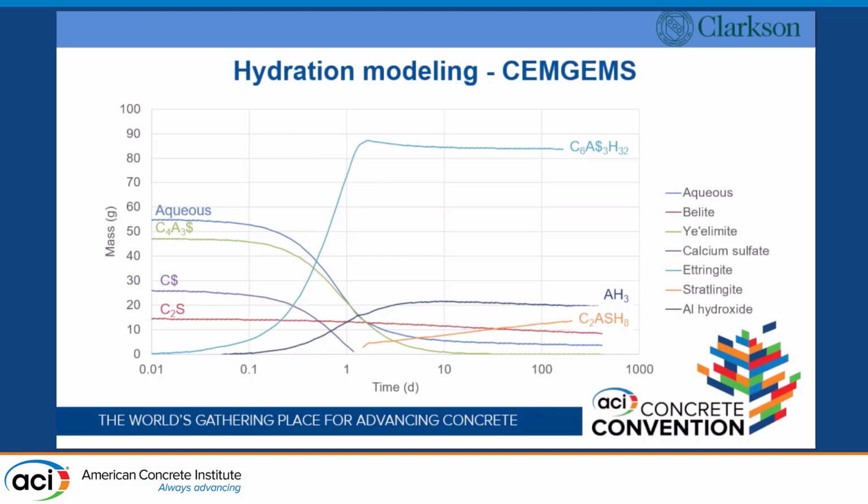So when we talk about passivating the steel, which we think is the issue, that's why we see early corrosion. Of course, the steel is not passivated. So when is the steel going to passivate? The steel is only going to passivate when the pH is elevated to a sufficient degree, right? We need a pH of something like 12 to passivate the steel. And this is the only hydrate that's going to carry with it some hydroxide ions to give us that passivation potential.